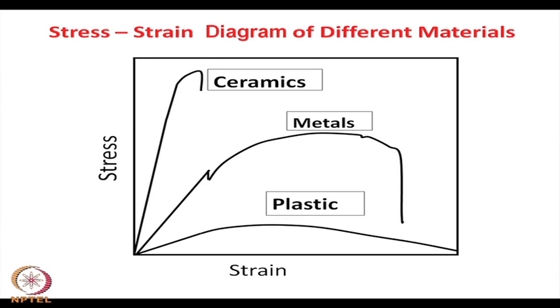deformation. And the characteristic of ceramics is that the elastic component is much larger, and it needs a very high stress to generate a small strain. Therefore, as the stress-strain ratio is the Young's modulus, the Young's modulus of ceramics in general is much higher, much larger than even for metals, but the plastic deformation is almost negligible.